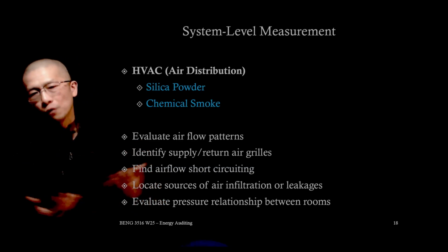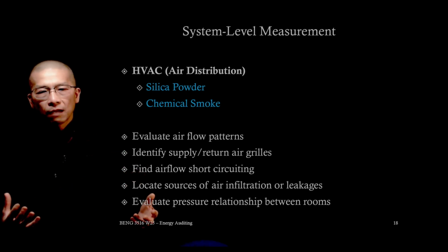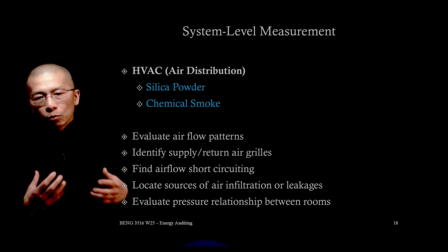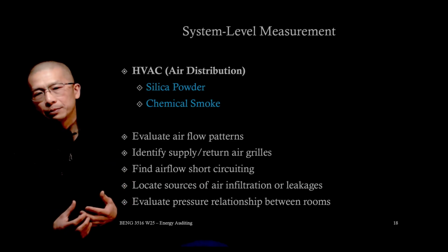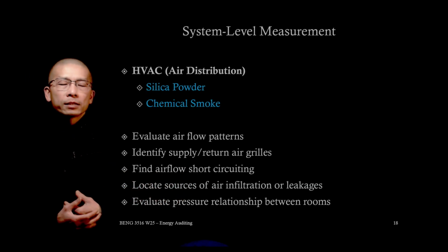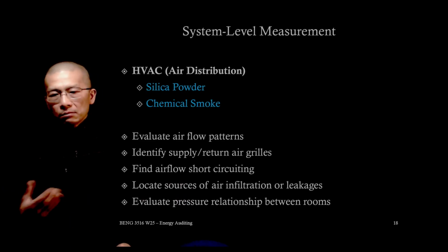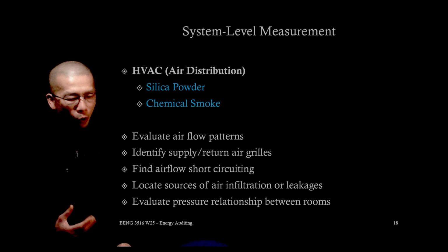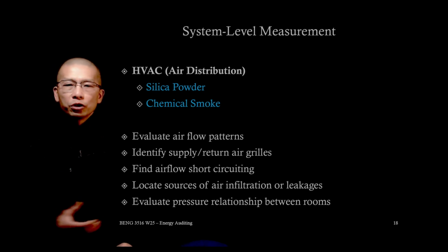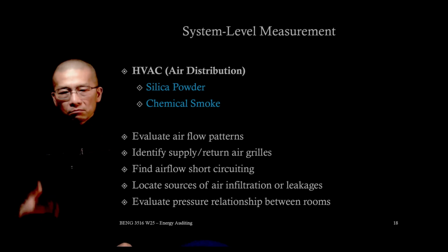Right? So overall, smoke and powder tests are qualitative diagnostics. They don't quantify airflow rate, but they are extremely effective for understanding the air distribution quality, which is often where comfort and energy problems originate.